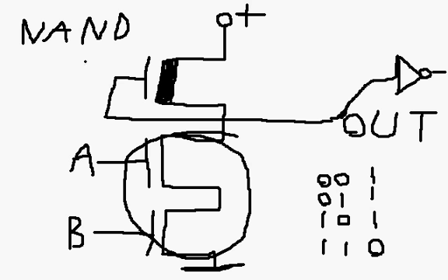Okay, next let me go ahead and do an exclusive OR gate. That should be fun. So the way that you do exclusive OR, I guess there are a few different ways of doing it. The way that the 6502 does it, if you look at the PDF diagrams, is it typically looks something like this. It has a structure that looks very similar at first to a NOR gate. So let's see how.